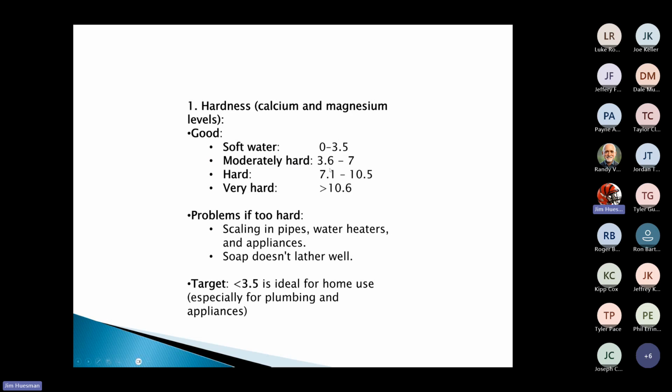But when we are testing for hardness, we're going to come up with a scale. Anything from 0 to 3.5 is what we would consider soft water. Then obviously it goes all the way up. And the reason I'm showing this is when we're looking at Cincinnati, I was just sitting in Cincinnati. I tested some water, was sitting around 8 grains of hardness, which is definitely hard. Definitely looking into some treatment, but it's nothing crazy. Drive 45 minutes to Miami of Oxford. We'll test their water, and they'll be sitting roughly around 32 to 43 grains of hardness.